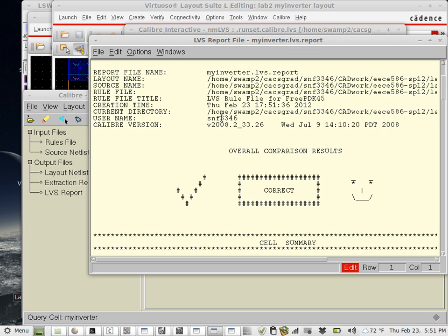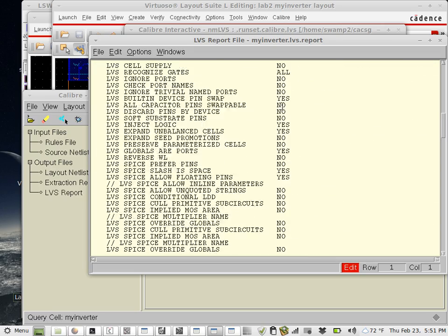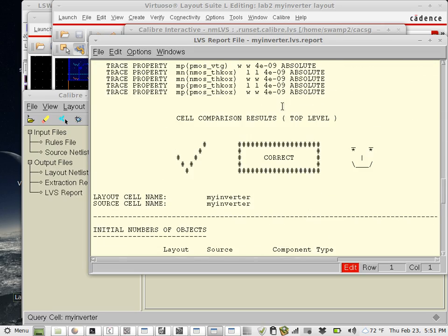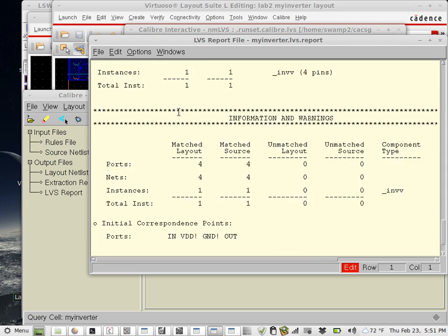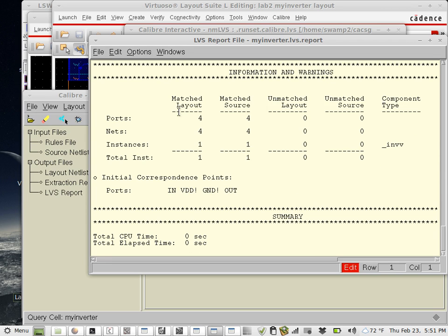That's why you need to extract the netlist from the layout and then use HSpice to simulate the layout with parasitics. Because some circuits fail to work entirely with parasitics inside of them. They may work in schematic but fail. And by the way, everything should be the same: the port and pin names, the widths, the connections, everything.